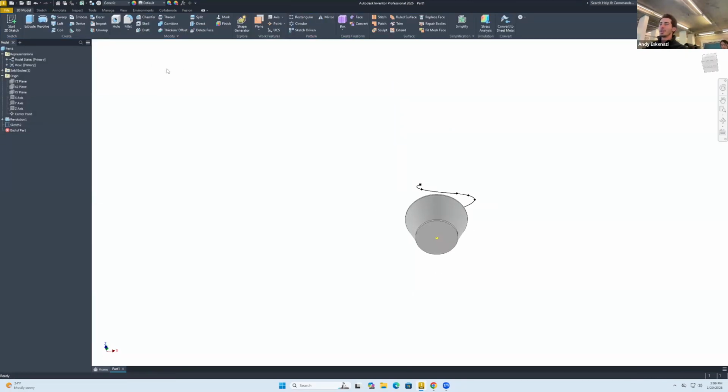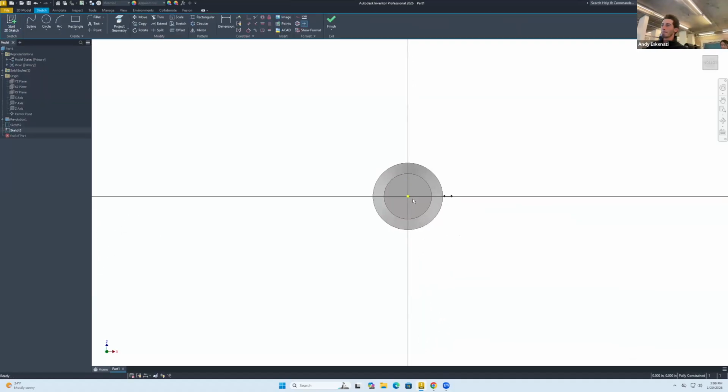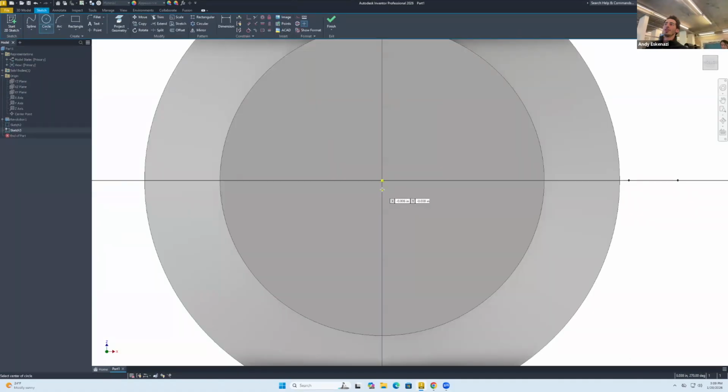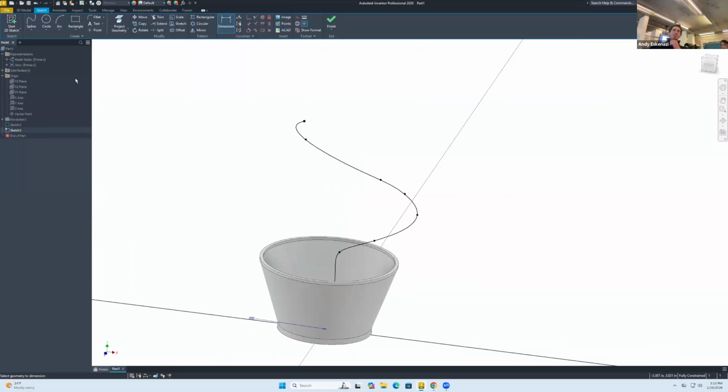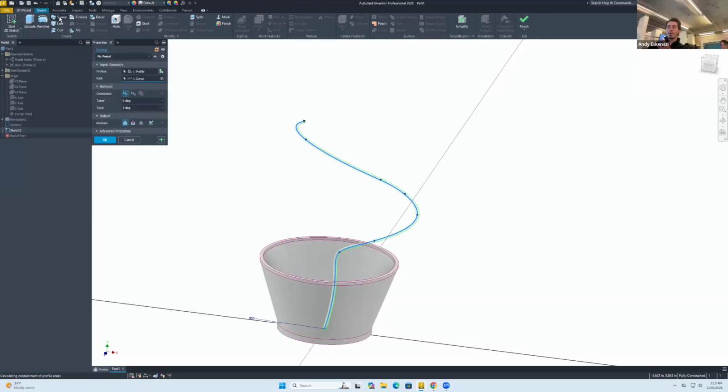And now what I'll do is I'll go here to sketch, I'll go here to this base, and I will do a tiny circle. And we'll give this a dimension of, yeah, that's fine, 0.5. Maybe I might make it bigger, it doesn't matter. But we go here to 3D model, then to this command that's called sweep, and it automatically recognizes that profile